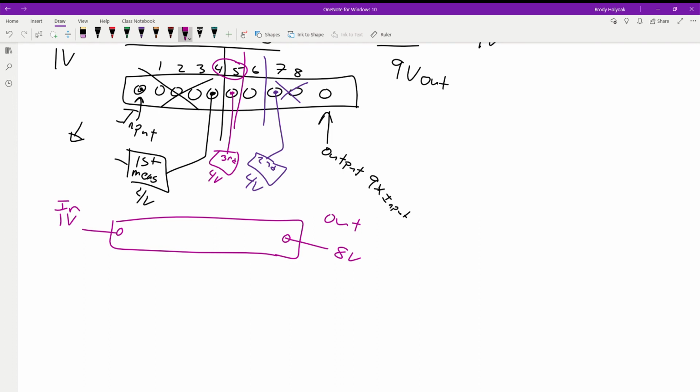So again, we're going to half split it again. We're going to check all the different stages: 4, 5, 6, 7, 8. So when we half split it, do you think it's probably safe to assume that these ones are correct? Yes. So we're fairly confident the problem's not on that side. Without even having to take a measurement, based on our previous measurements, that side's good. So now we've got these ones.